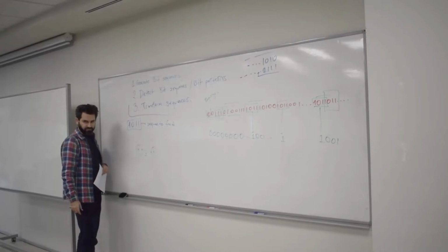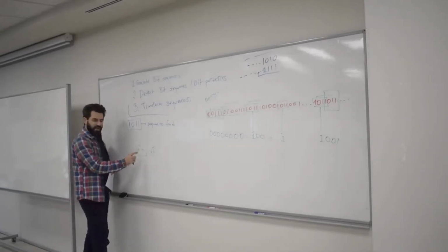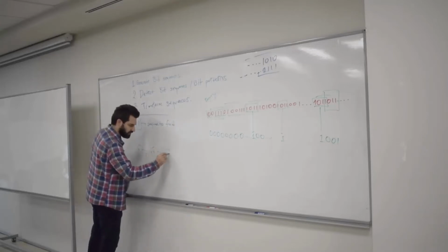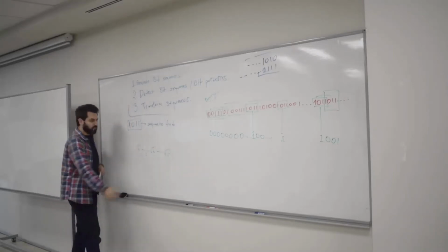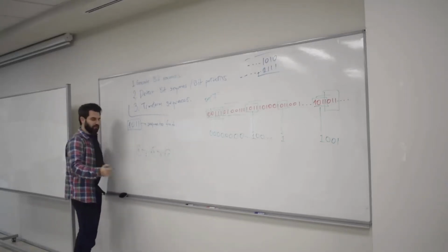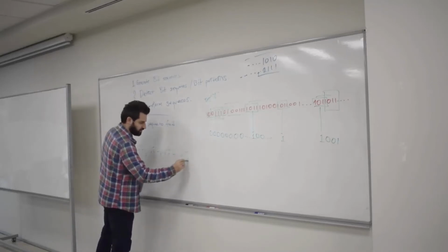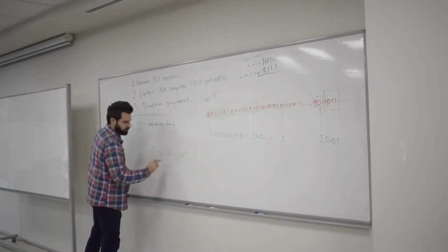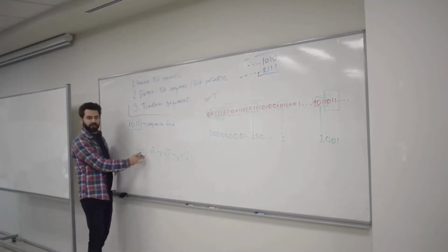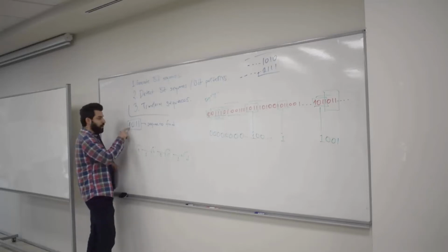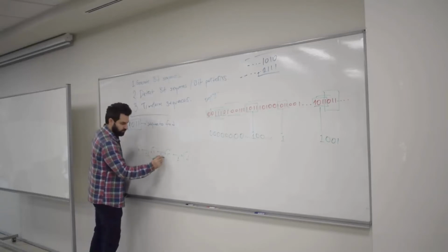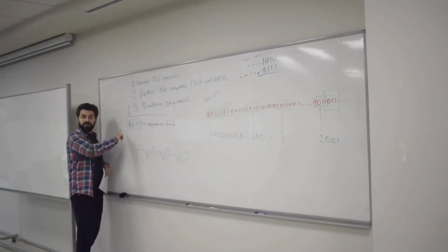I have got two states, and I move from this state to this state when I see a 1, and then I have got another transition from this state, B state, to C state when I see 0. Okay, let's just write it down. And then I see another state transition when I see 1. Okay, and of course, I have to think about the outputs as well, right? Because when I see for the first time a 1, I should output a 0, right? So I'm going to have a 0. And this is also 0, and this is also 0. Okay, I haven't completed my sequence yet.